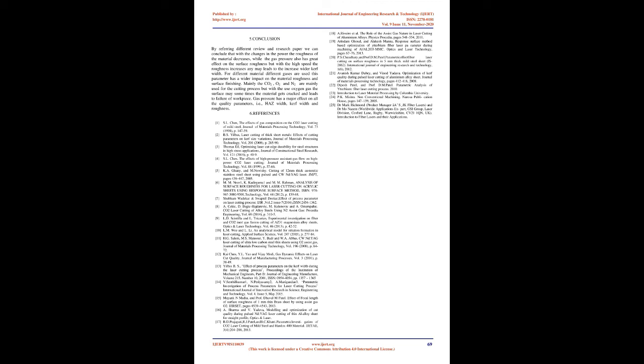To avoid any influence of the surrounding atmosphere on the cut, it is suitable to measure the recast layer using a microprobe, and then to perform a microchemical analysis. We recommend that increased attention be paid to a study of the recast layer and its dependence on cutting parameters. It would be suitable to perform the microhardness measurement at the melting boundary of the original material, and more importantly, on the recast layer itself. Our paper has contributed a comprehensive view on the influence of the process parameters on a narrow group of materials used in the aerospace industry.